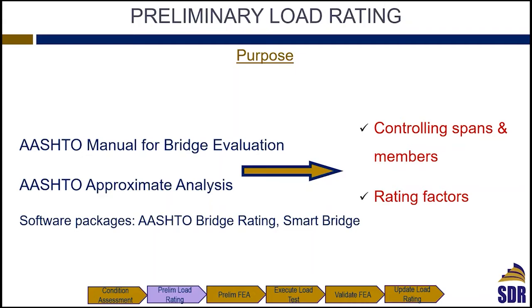And this is mainly we do a conventional load rating analysis, same as what we do for any bridge, using the AASHTO approximate analysis methods, and also using many software packages like AASHTOWare Bridge Rating. We can do it with SmartBridge, which is a software that we also develop in-house. It can be with MIDAS as well.